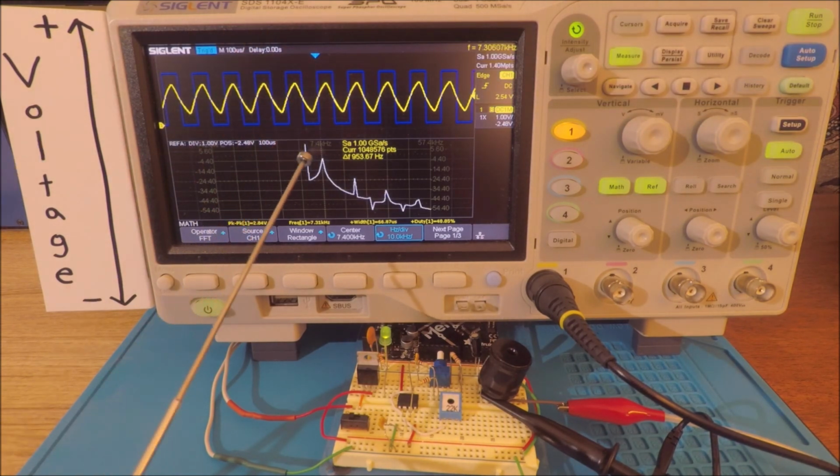Here's the fundamental at 7.3 kilohertz. That happens to be a value of -4 decibels. And then here's the second harmonic, which is at -24 decibels. So the second harmonic is being suppressed by 20 decibels from the second order resonant filter. Next one over is this one right here. That one is at -34, so 10 more decibels down from the previous one, and so on and so forth. Being a second order filter, we're rolling off those higher order harmonics at 40 decibels per decade.